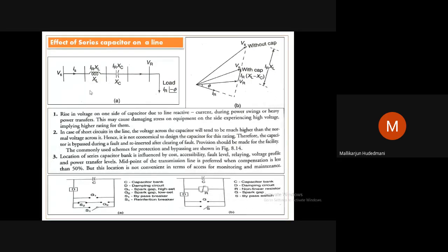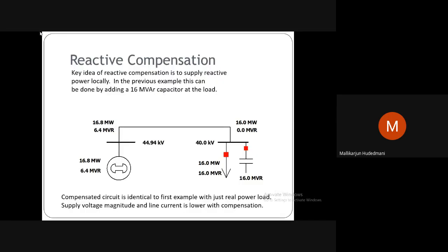If we do not incorporate protective mechanisms for the capacitor, probably the incorporation of series compensation fails. So it should not go that way. A technically feasible solution means that when we install a compensating capacitor, we must incorporate the associated protective mechanisms. This way, it can be viewed as one of the best compensation concepts for the capacitor in series mode of operation. Then let us see how the shunt capacitor concept works out here.